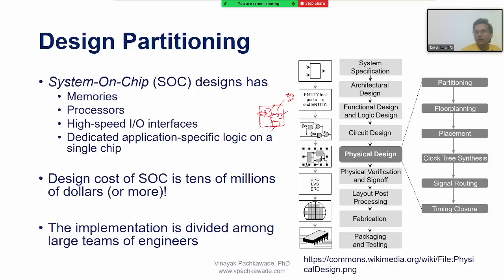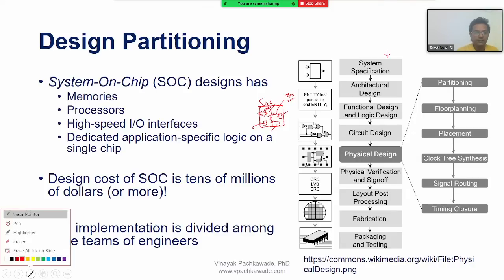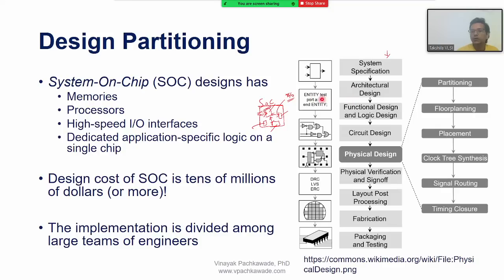So this chip will also contain them, and you have to design them. And also it will have some application specific dedicated logic. Let's say this would be analog, RF, or mixed signal block, something like that. So this complete block will be called an SoC, right? So right here in this block diagram, we are seeing that the first thing they will start with is describing the architecture. We will see in a moment what the architecture is. So the team will start writing, using some programming language, as I mentioned earlier, hardware description languages.